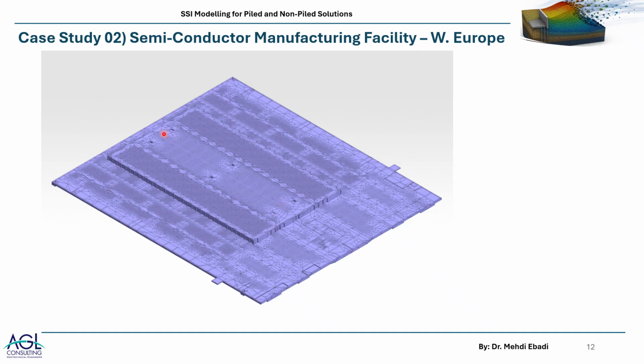And the mesh is refined in the areas where we have columns and loads, and has larger size in the areas which are under generally area or line loads, which, as we know, is what we normally do in finite element modeling for getting more accurate results in the areas of interest, in this case, the column forces.